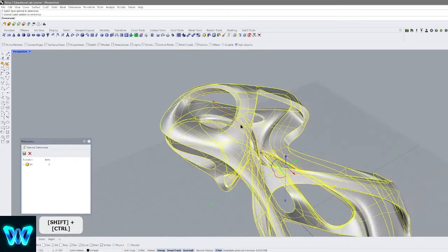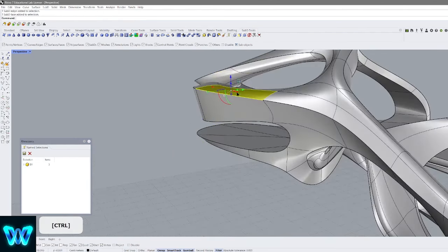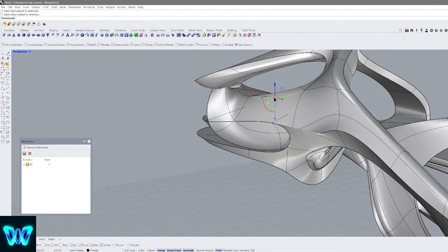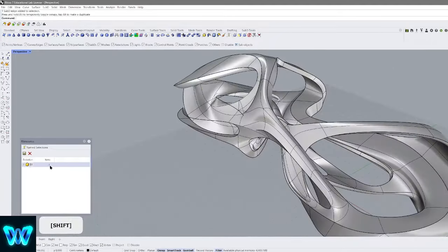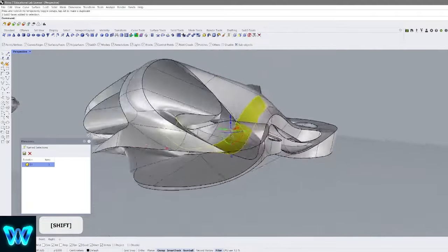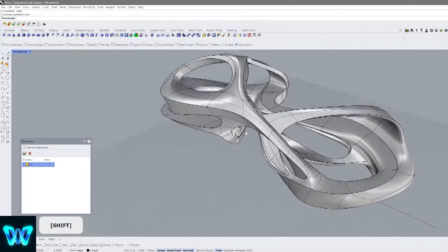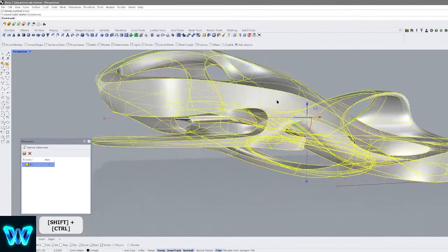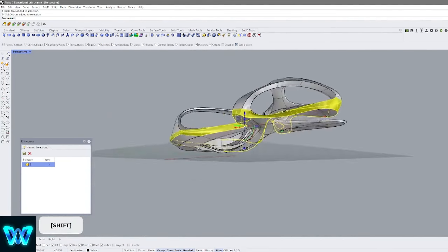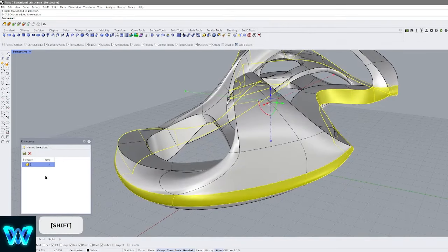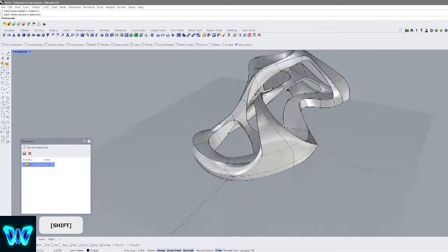And so then I can keep on modeling whatever I'm modeling, making changes, and things move around, whatever. I'm just messing it up. And if I want to go back to those 3 faces that I had selected before, I can just click here and it'll always bring me back to those faces. So it's really useful when you're creating very complex things. For example, you have an edge loop which you don't want to lose. The moment you add more stuff, you might lose that edge loop, so you want to save it as a selection. Same thing with edges and vertices.